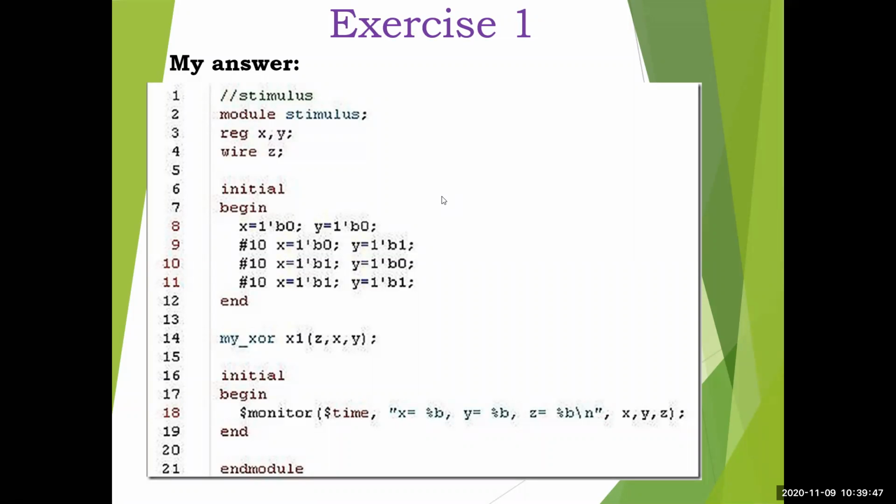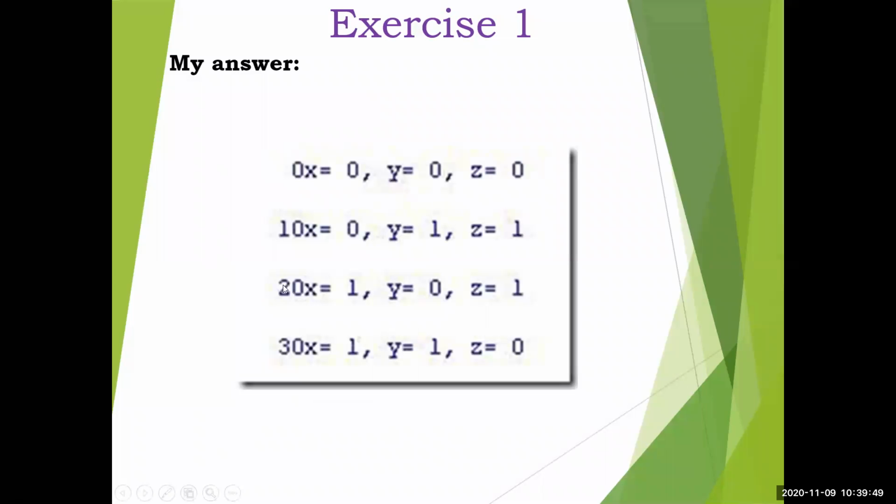So if we see the simulation output now, at the 0th simulation time, you have the x and y inputs 0 0, so output is 0. Okay, then at simulation time 10, that is 0 plus 10, the input is changed to 0 1, so z is changed to 1 now. Even you can pass these values through each individual gate, the NOT gate. Okay, how it will change the value you can observe.